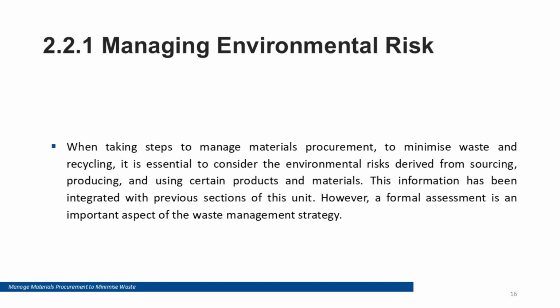Waste practices can create environmental risks, such as contaminated runoff, dust, or improper storage of hazardous materials. Environmental risk management involves identifying risks, assessing likelihood and impact, and implementing controls. Controls commonly include segregation, bunding and containment, covered storage, spill response procedures, and using licensed transport and disposal providers. Clear controls support compliance and prevent incidents that cause clean-up costs, delays, and reputational damage.